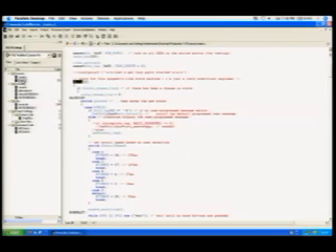So everything has to be completely mapped out, well before you even write a line of code, for what your memory requirements are going to be. Now, this one had a lot of extra strings in there for his Easter eggs and some other useless stuff that I saw. When I took that out, I was able to free up a 30-character buffer for the scrolling display. You'll see I have up, up, down, down, left, right, B, A, B, A, select, start, fully displayed.